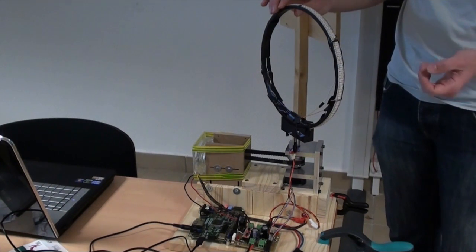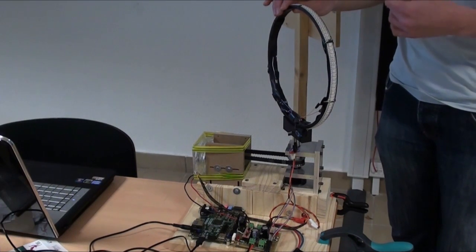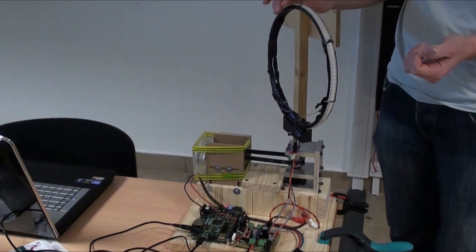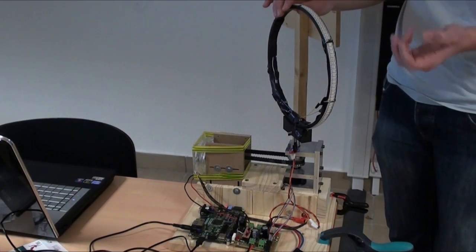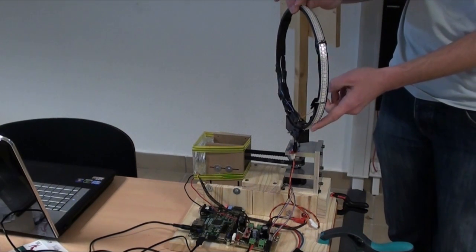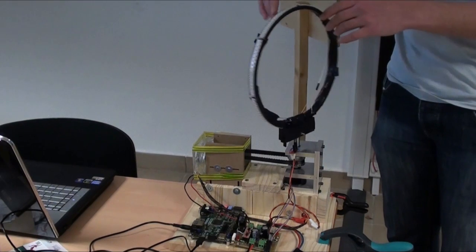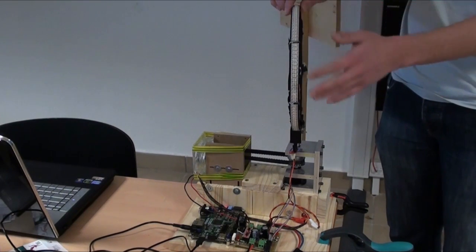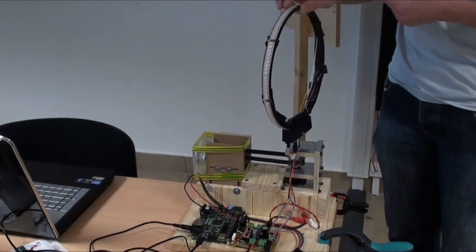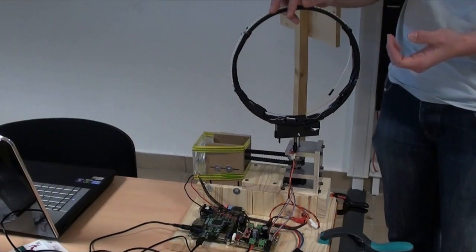Those strips need 24 bits per pixel sent with a serial protocol. This protocol is relatively slow, and as we want to rotate the globe at least 10 rounds per second, we need to split it in several LED strips, 3 exactly. We also use the other side of the ring to display the opposite column, enabling us to double the frame per second rate and to balance the ring mechanics.